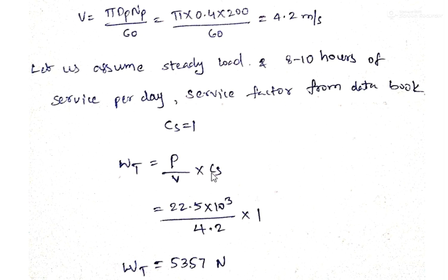and that you can substitute here, and here CS is the service factor. This we have to take from the data book. Let us assume a steady load is acting on this gear drive, and these gears are working 8 to 10 hours per service day.